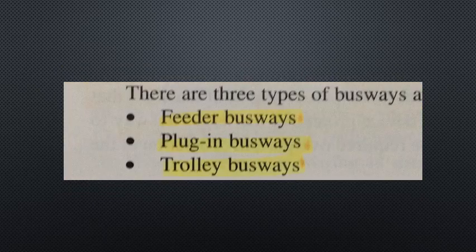Auxiliary gutters, essentially identical in construction and appearance to wireways. Auxiliary gutters are primarily used to extend or supplement wiring spaces at load centers, transformers, and metering cabinets. Auxiliary gutters cannot extend beyond 30 feet from the equipment they supplement. The same rules regarding fill 20% and splices or taps 75% apply as with wireways.